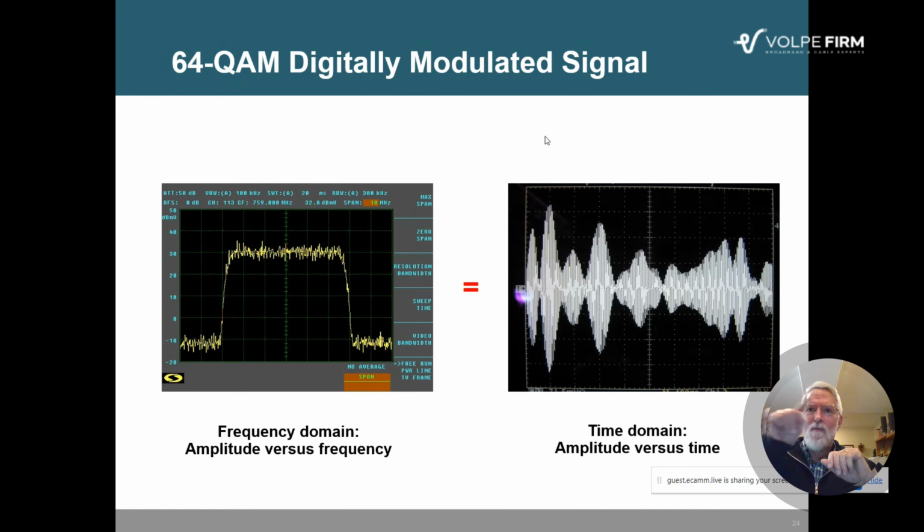You can actually see where the phase shifts, because with QAM, quadrature amplitude modulation, you're actually varying the instantaneous phase and amplitude of the signal to represent different symbols or groups of ones and zeros. So you can see that this burst on the left, if you will, represents a symbol. So it's got a certain amplitude and phase. And then down here, the phase shifts and the amplitude gets a whole lot bigger.